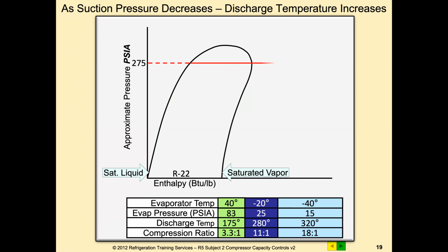Hey, Jim. Sorry it took a bit to get this off of mute. One thing I have run into over this past 6 months, with some of the Copeland condensing units that are now coming out with essentially the Dixell controller, they've got a thermistor located on the discharge of that compressor for compressor protection.